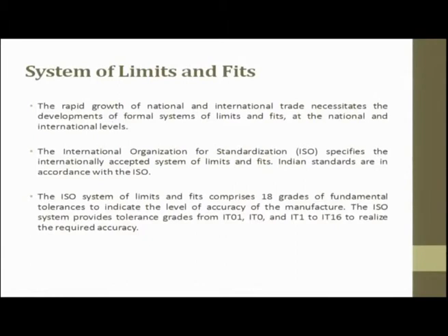The International Organization for Standardization, ISO, specifies the internationally accepted system of limits and fits. Indian standards are in accordance with the ISO. The ISO system of limits and fits comprises 18 grades of fundamental tolerance to indicate the level of accuracy of manufacture. The ISO system provides tolerance grades, IT meaning international tolerance, from IT01, IT0, IT1 to IT16, to realize the required accuracy.